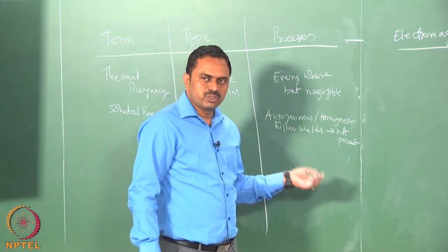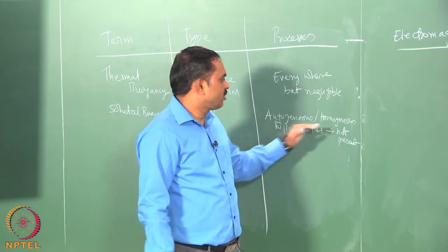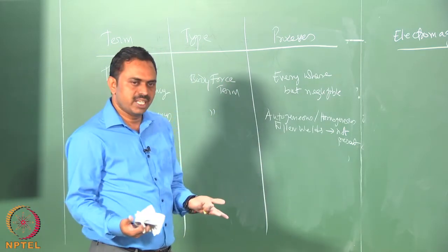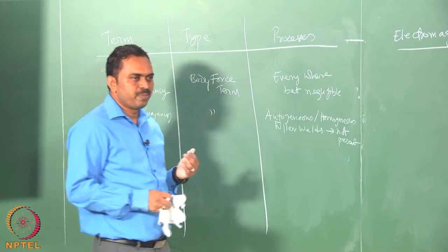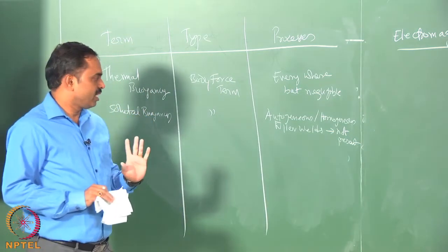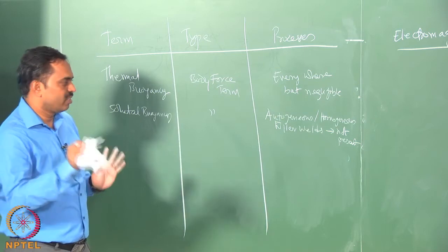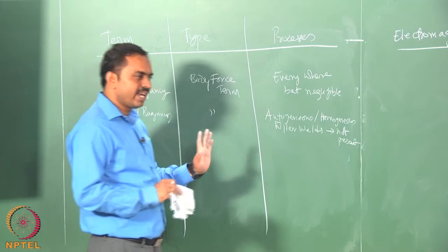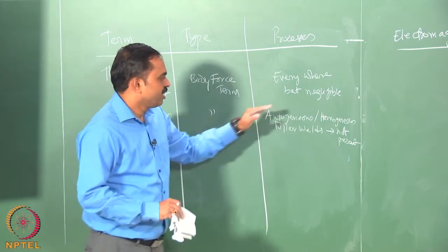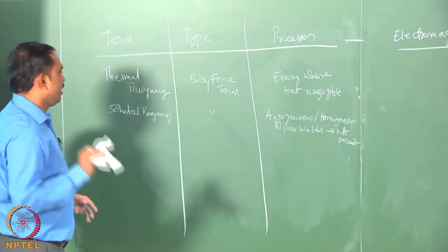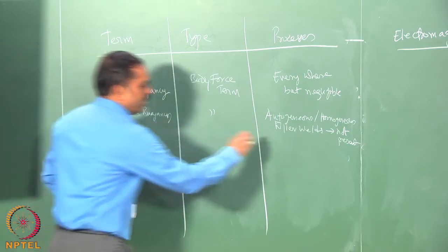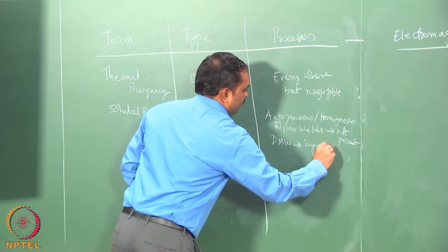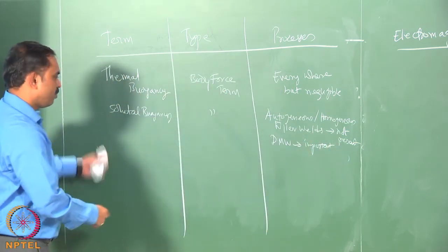And if you are also going to do a welding with filler, but the filler is actually homogeneous filler, which means the same material as the base material, then again there is no concentration changes and therefore there is no solutal buoyancy. In the dissimilar welding it is very strongly present because there is a strong composition change across the melt pool, and in the situations where the filler is added which is different from the base material, again it is present. So, it is not present in autogeneous and homogeneous, and it is present in rest of the situations. And in the dissimilar welding, I would say it is important. Okay. Now, what about Marangoni?